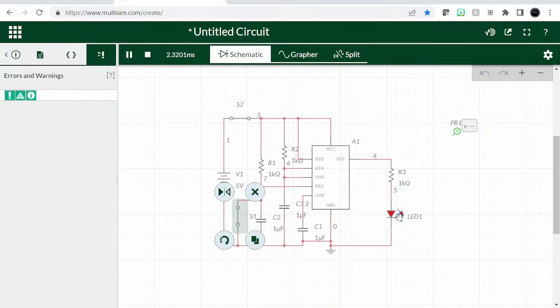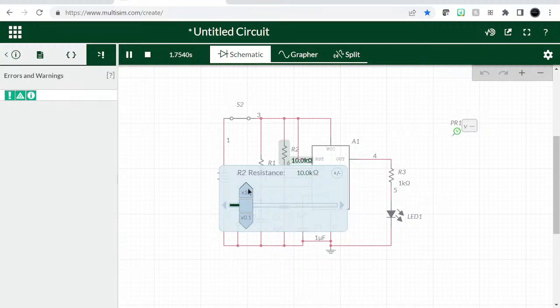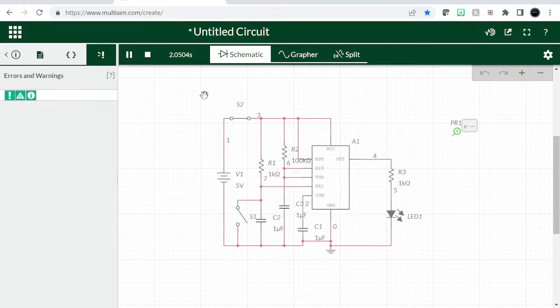All right, it's constantly blinking, but that's not what it's supposed to do. Okay, I'm supposed to just close it one time. Yeah, so sorry, I'm supposed to press it and release it. Yes, close and then release. But the monostable period, the time is too short, so let's increase that so we can see the effect. Now it's gonna stay on for the time. This value is still too small, so let's increase this a little bit, make it 100.